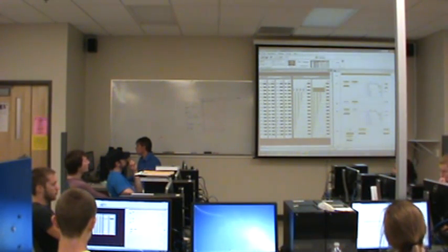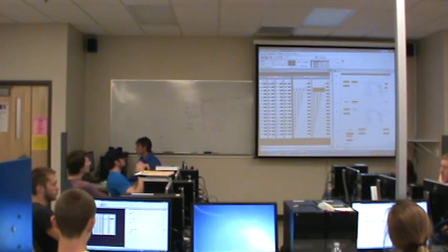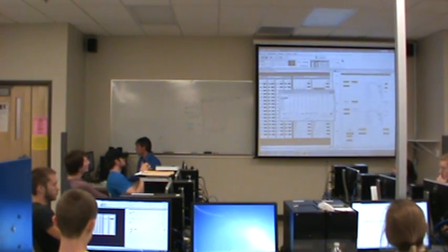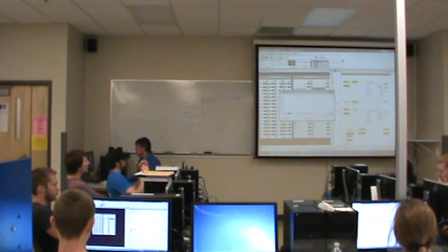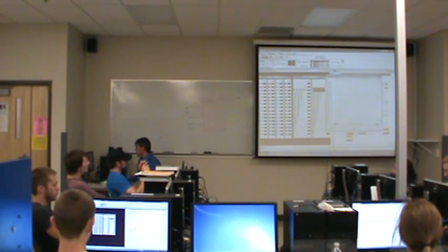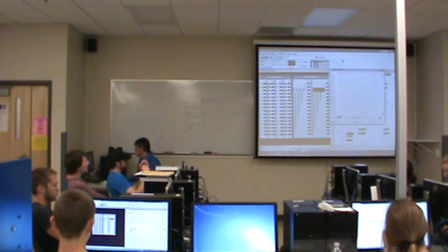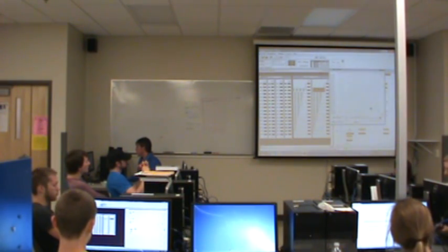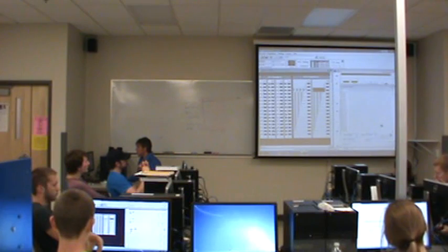Notice that all I did is I went to 0007. If you look at memory, the binary file, I want to look at it in binary. There is one more step in the sequence. The sequence output has the opportunity to turn on bit 3, which is right here, and turn off the other bits. That would put an 8 here in the display.